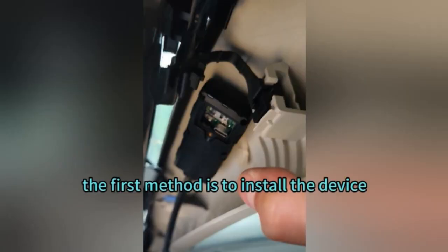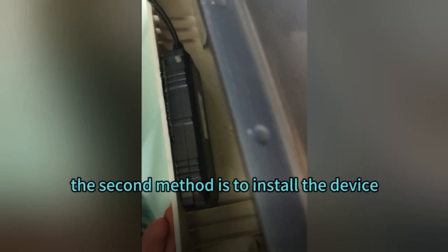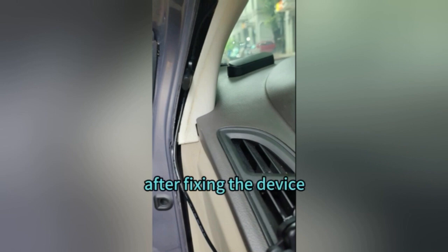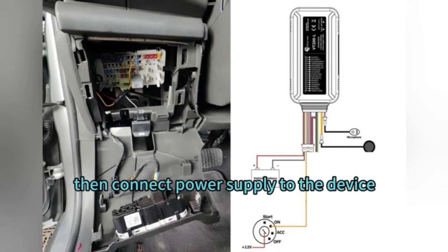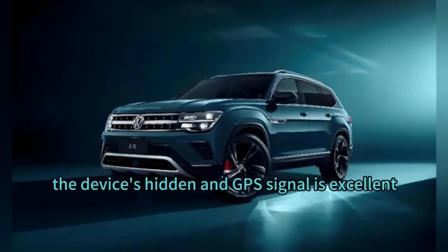The first method is to install the device on the top of the panel, and make the device front side face the glass. The second method is to install the device at the bottom of the panel. Also need to make the front side face the glass. After fixing the device, run the wire through the plastic gap. Then connect the power supply to the device. Now put the plastic panel back to its previous position. In this way, the device is hidden and GPS signal is excellent.